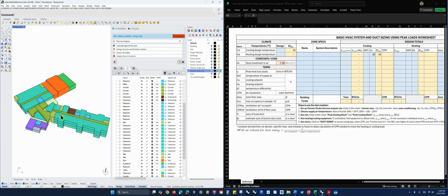Once there, though, it's a school. I can see why then they said, let's now bring in outdoor air and heat and cool that air and supply fresh air through air so that we have a simpler system. We can just plunk down these mechanical AHUs on the roof wherever we need them, go straight down with our supply and return ducts. It's pretty straightforward, and this is a utilitarian building. It's a school. We have a lot of roof area. It's not like people can see it or need to use that part of the building. So it makes sense to me why they did that.